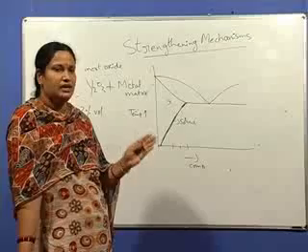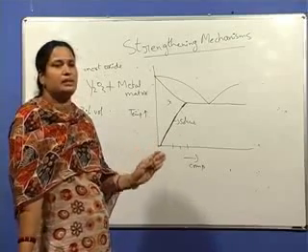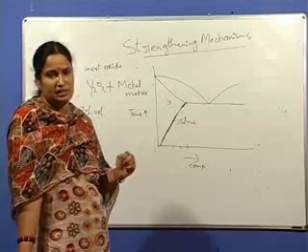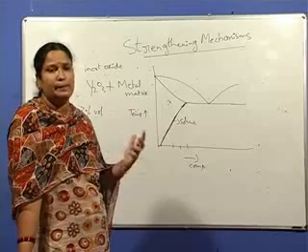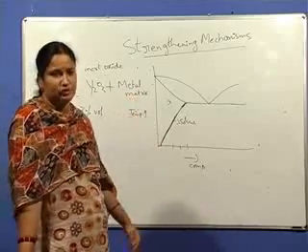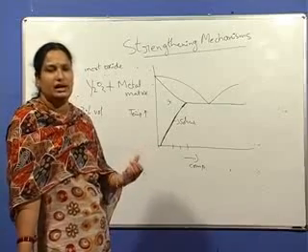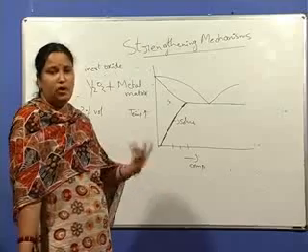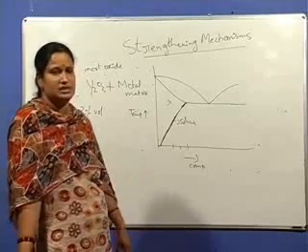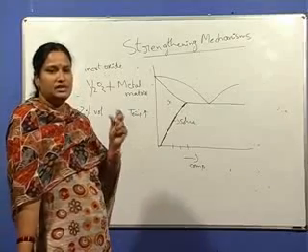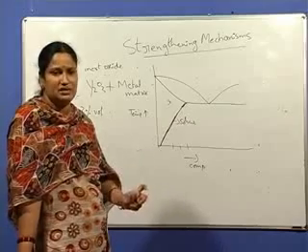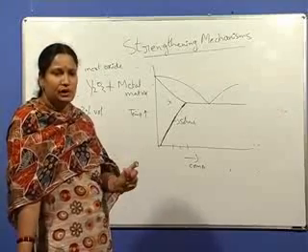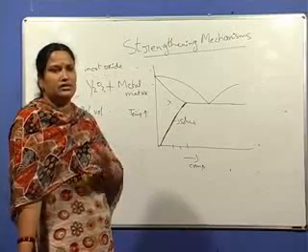In the case of precipitation hardenable alloys, the alloys need to have a sloping solvus, and the precipitate needs to be coherent with the matrix. Whereas in the case of dispersion strengthening, one can theoretically produce an infinite number of dispersion strengthening alloys. Why? Because it is only mechanical alloying, mixing of metal matrix powders with the inert oxide particles, ball milling, and then consolidation by powder metallurgical techniques and forming the product. There is no coherency between the dispersoids and the matrix in dispersion strengthening alloys, but there is coherency, or lattice matching, between the precipitate particles and the matrix.